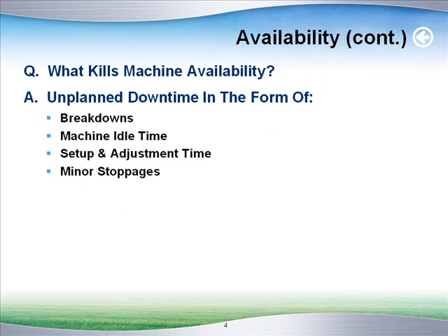Okay, what kills machine availability? Well, unplanned downtime. It's pretty basic, right? Okay, well that comes in the form of breakdowns, machine idle time, setup and adjustment time, and minor stops.